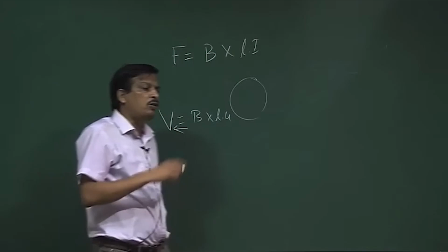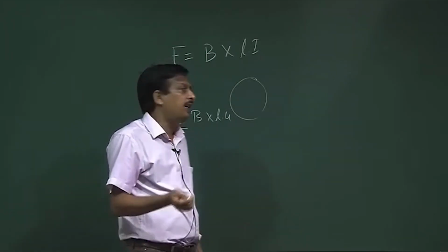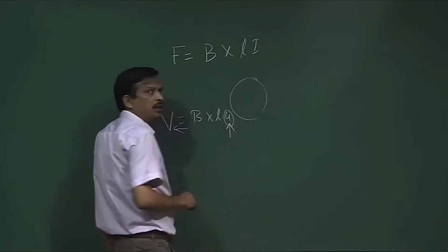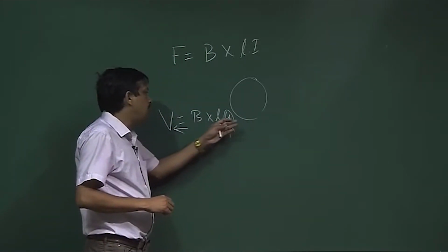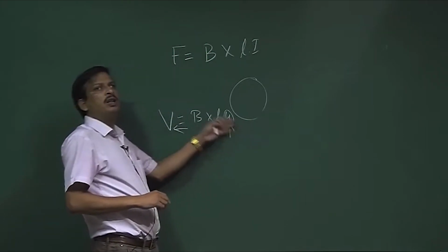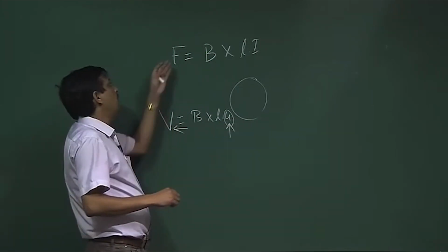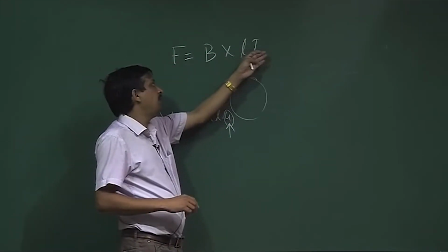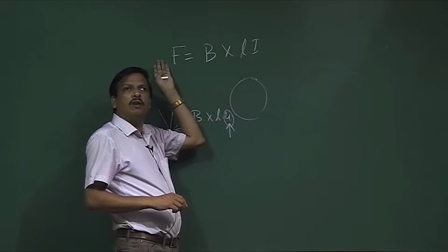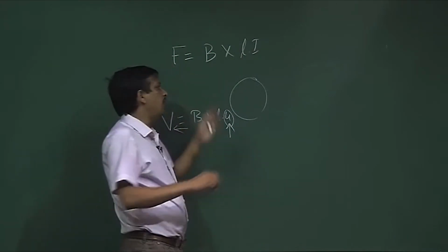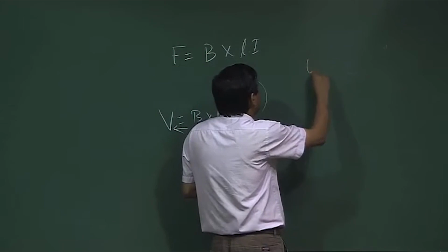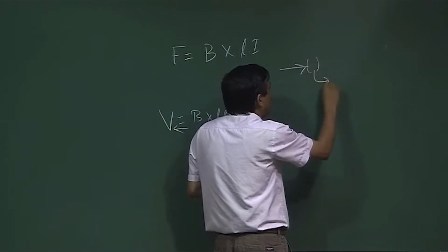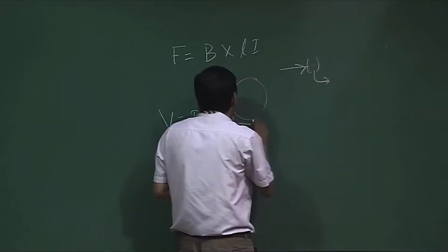So, by an electrodynamic principle, I can convert this acoustic velocity. I can convert that mechanical velocity to electrical voltage, or mechanical force to electrical current, and electrical current to mechanical force. Okay. So, in case of a microphone, I want the mechanical force to be converted to an electrical signal. So, I use this equation.